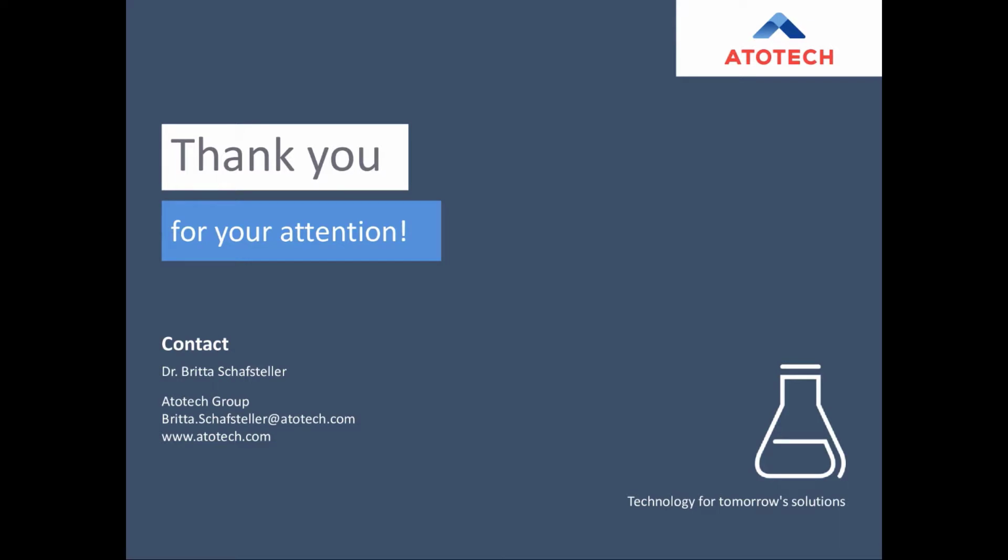Okay. Can you please describe the evaluation procedure for the corrosion in more detail? Yes. As I said, typically we study 8 to 10 PTHs, and for each PTH we check a minimum of 7 locations, which are the 4 locations at the corners or the entrance of the PTHs, and then 3 locations at the PTH ring.